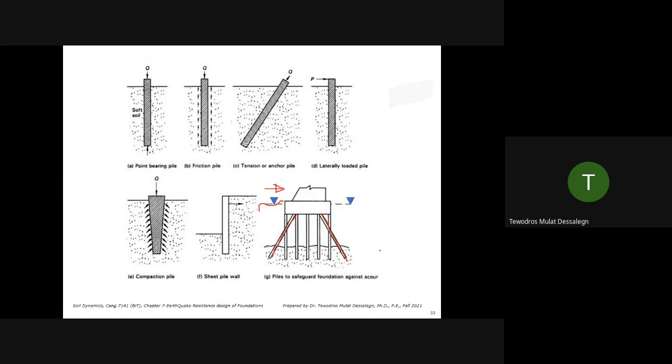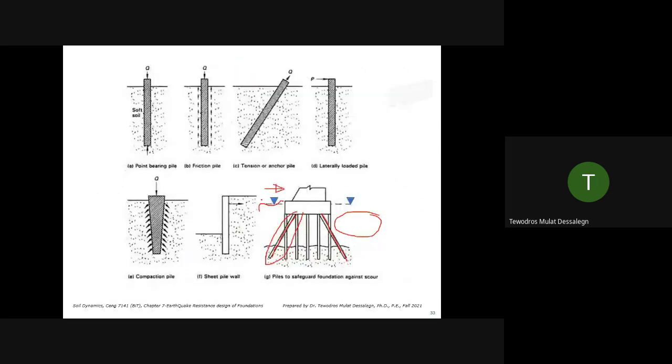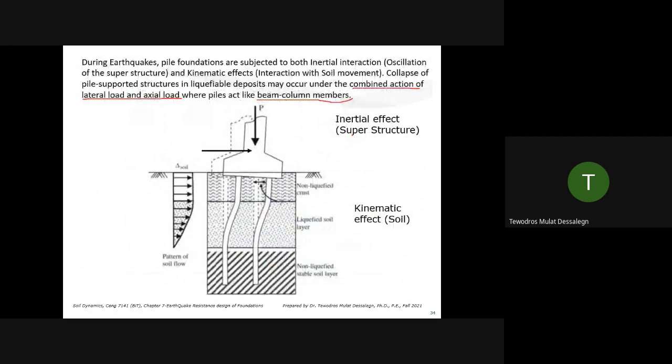And we can use this orientation of piles also for liquefiable soil. If this soil is liquefiable, usually we don't credit it to resist the loads, but instead we may even consider applying load on the piles. Those lateral loads can be resisted by orienting piles in different configurations. So you can go through this write-up; it's pretty much what I just discussed.